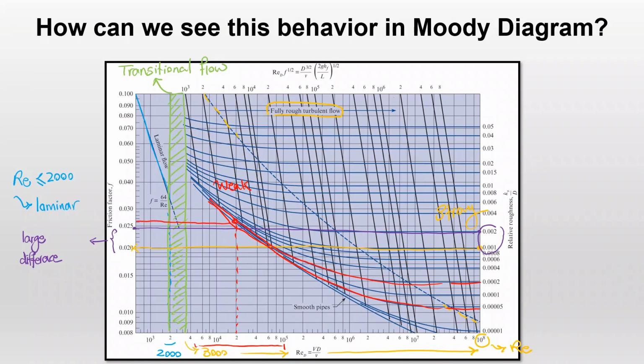So this is telling me that whenever Reynolds number is in the lower spectrum of turbulent flow, whenever your turbulence is weak, friction factor between pipes of different relative roughness is not going to be way different. However, when turbulence is strong, in other words, when your Reynolds number is way high, even a slight change in relative roughness is going to change the friction factor by a lot.